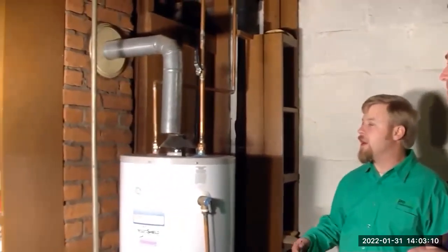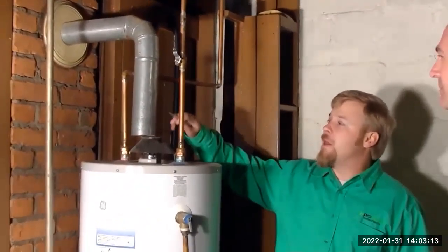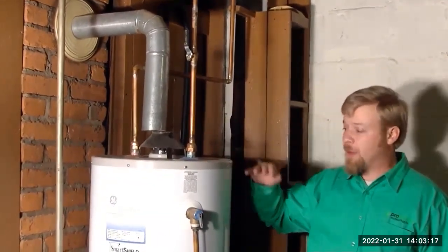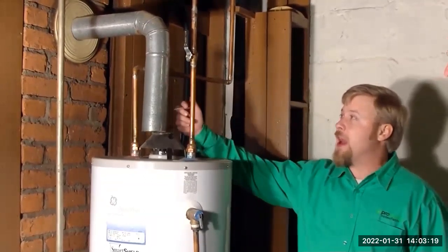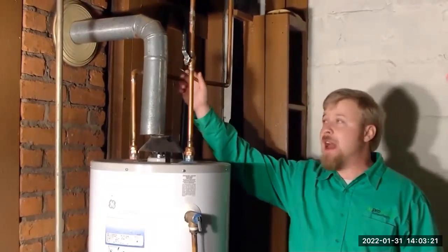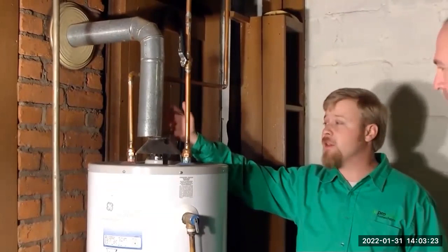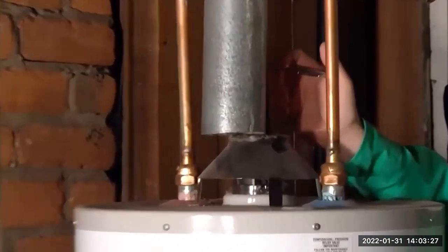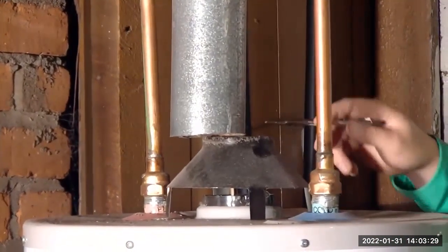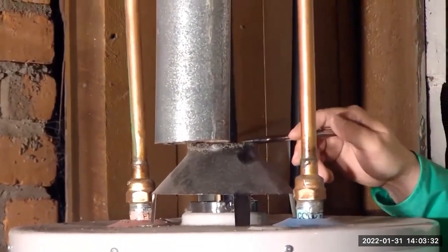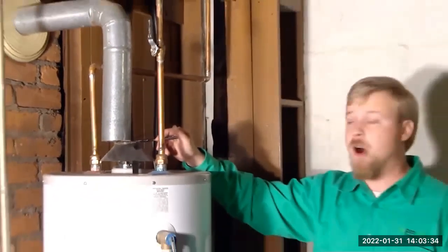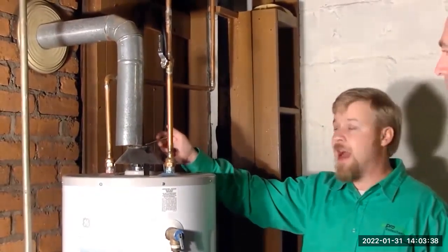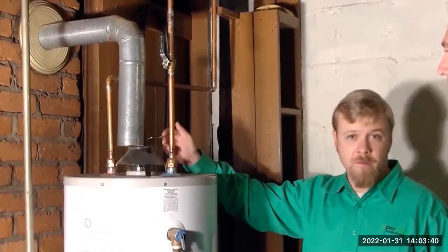Well, what we found here, Don, is I was looking around, I actually saw the chimney for this gas water heater. So obviously it uses combustible gas, and you actually have to vent those gases outside of the home. Like you said, this is a serious safety issue. It can cause serious illness or even death. And as you can see here, this pipe is actually disconnected from the water heater itself. So you have those harmful carbon monoxide gases actually inside the home itself.